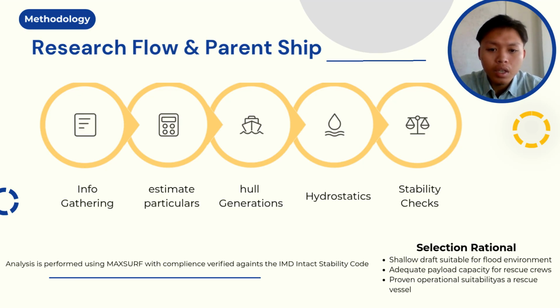new design. The third step is hull generation using Maxsurf software, where the initial 3D hull model is created. The fourth step involves hydrostatic calculations, which evaluate buoyancy, displacement, center of buoyancy, and other hydrostatic characteristics.